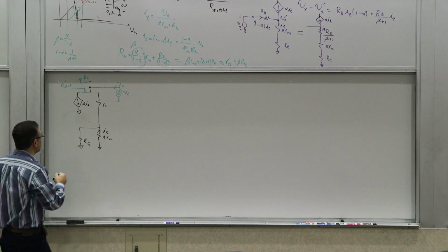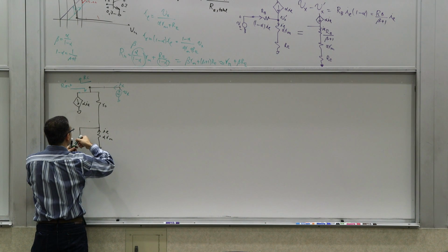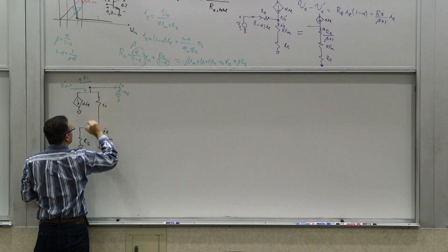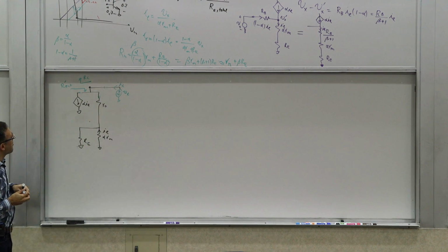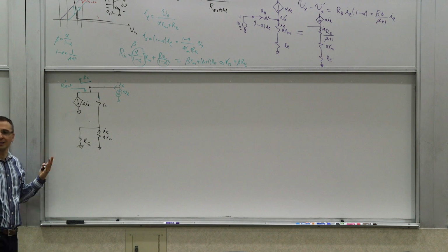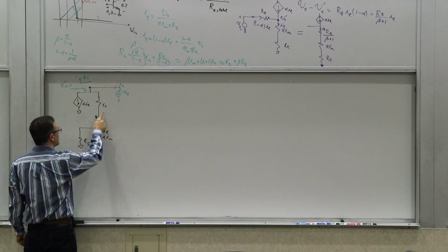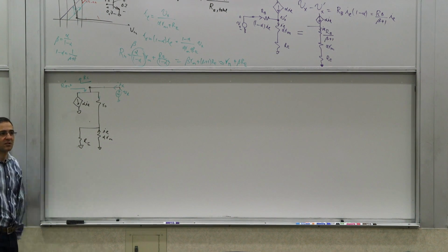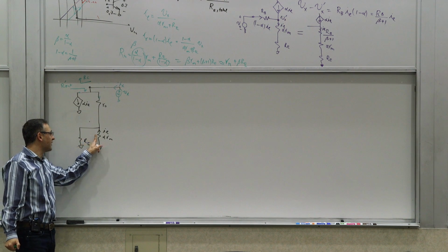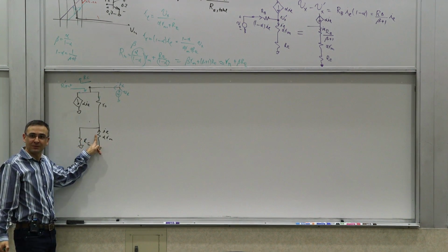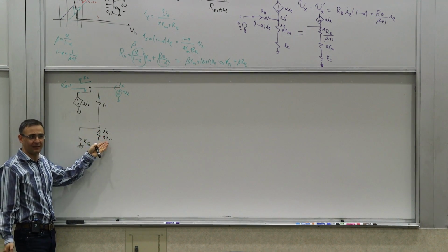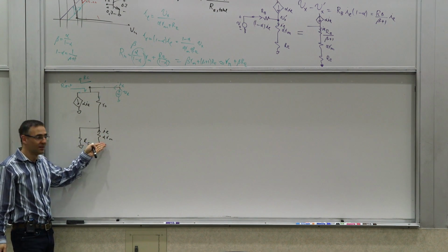So the first thing we need to do is estimate the current through this branch. It's Vx divided by the resistance of this combination of these three resistors, right? This current we're trying to find out. Now, if you were just doing things blindly, it's a parallel combination of these two in series with that. We can write it like that. It would become a little bit of a messy equation. You can solve it and then simplify it. Or you can make an observation about the relative sizes of these values. Do you agree that this parallel combination cannot be greater than alpha Rm or Rm? So at the largest it can be is Rm. I mean, it can't even be Rm, but fine. Let's say it's Rm. What is this?